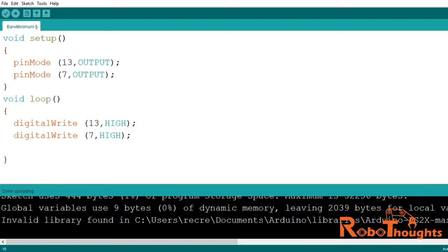In our circuit for this particular lesson, we are using two LEDs, pin number 7 and pin number 13, right? So that's why we just need two digital write output. Now if you are connected with say 10 different LEDs, you will need 10 different digital write to be input in your code here next to each other, all right? That's how it works.